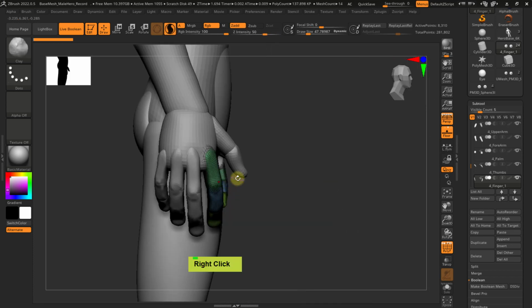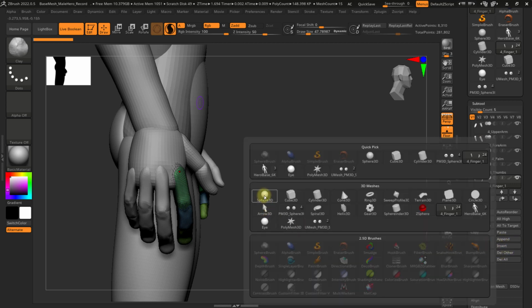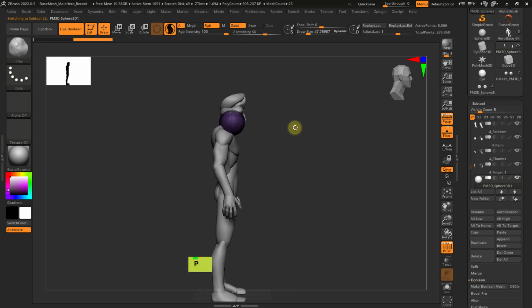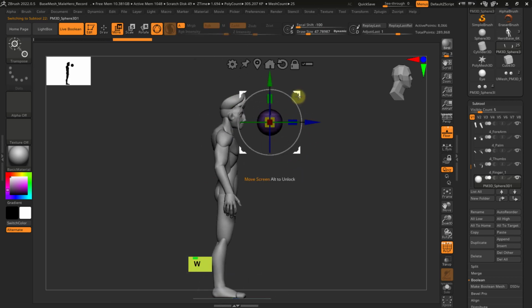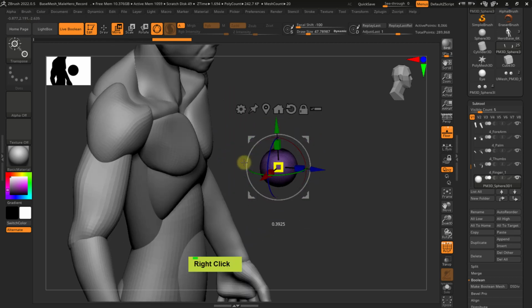When you have meshes that you don't really want to weld right away because you want to move them independently and fine-tune things, what you can do is create a few pieces, then merge them together and then sculpt as one unit. Now how to do it? So Subtool, Insert, and I will simply insert the Sphere 3D. Let me pull this in front, and yeah, it's a huge one, so it's time to scale it down.